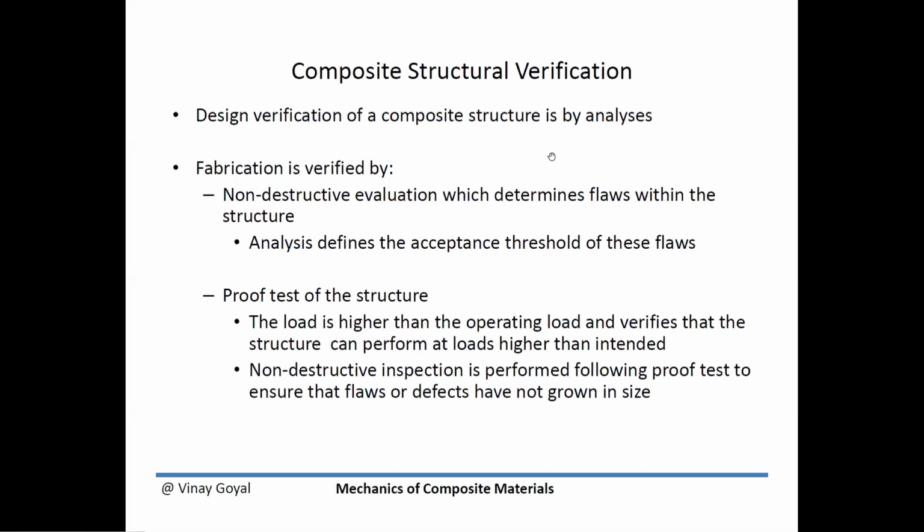You have the process controls, making sure you have a fault prevention plan, basically ensuring that you don't get contaminants within the composite as you make it, making sure you keep the shop clean, keeping the procedures up to date, making sure your build paperwork is robust. All the things that will come into making a composite, you want to make sure that those processes are robust.